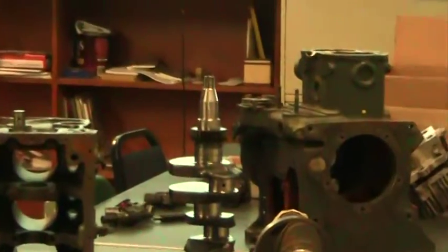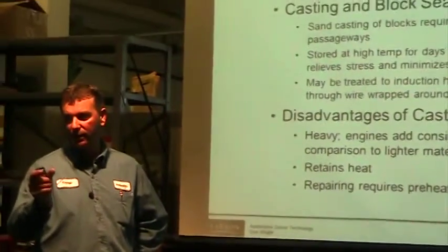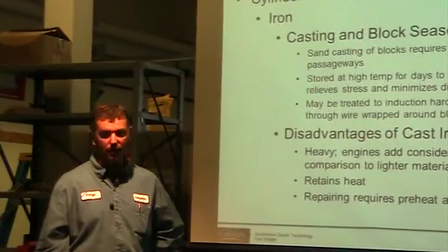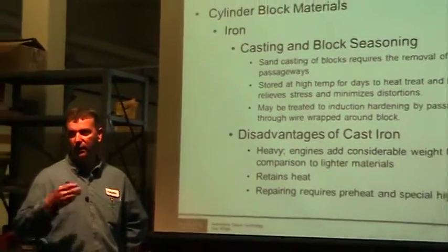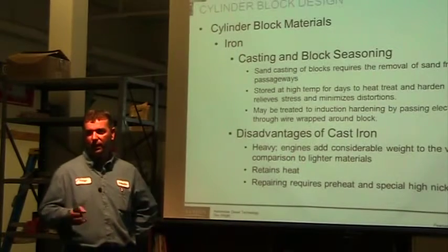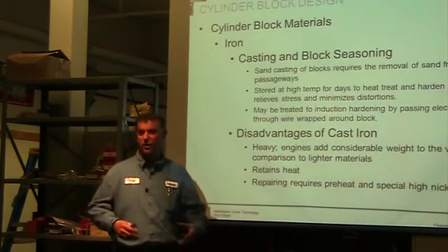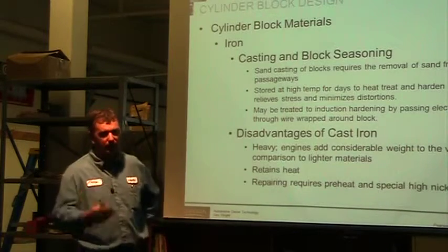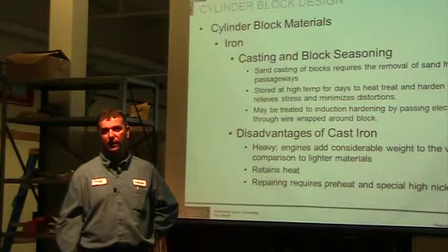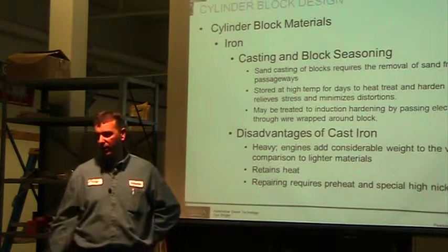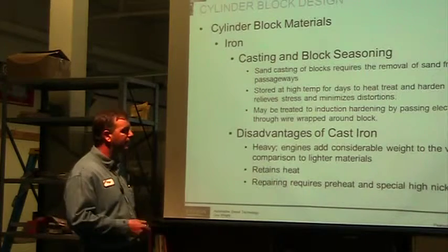It retains heat really well. So you have a block that's really thick. Anytime the metal is thick, it's going to hold heat a lot longer. So if I'm running my engine and I shut it off and every half an hour I come back and run the engine, it might be nice to hold the heat in there so that I'm not getting a cold engine every time. But if you're putting this thing to work and it's just going to work for 8 or 10 hours in heavy heat, that would be a disadvantage. So for the most part, it's more of a disadvantage than it is an advantage.